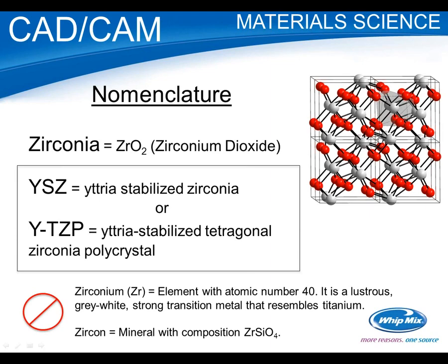Though they're both technically ceramics, porcelain starts as crystalline minerals, and when it's heated, it basically melts and fuses into an amorphous, glassy substance. So porcelain is closer to glass. Actually, zirconia is not. Zirconia stays as a crystalline mineral.